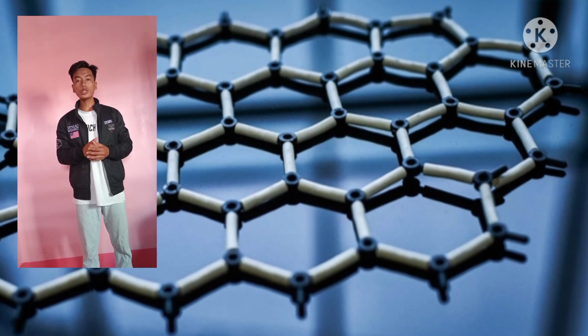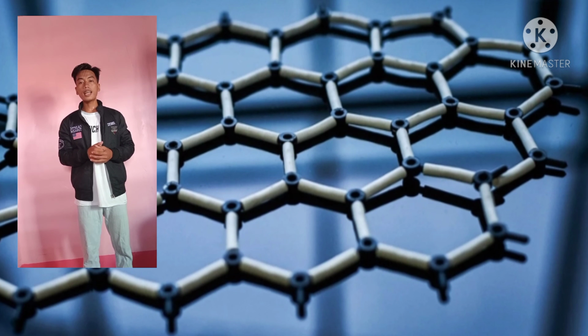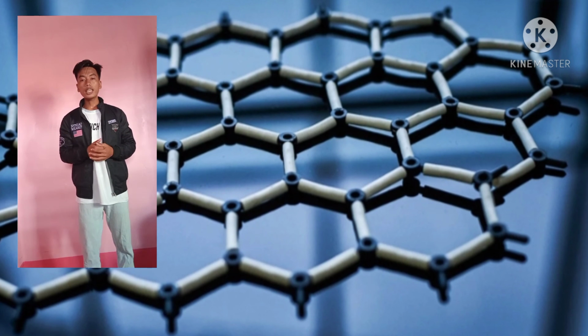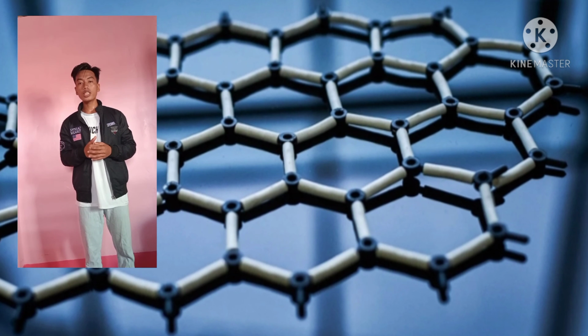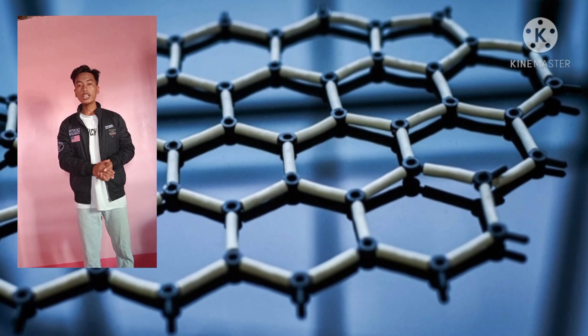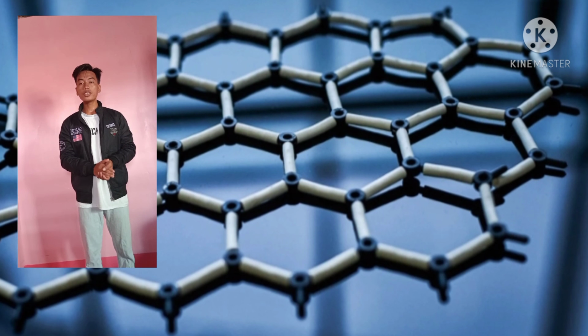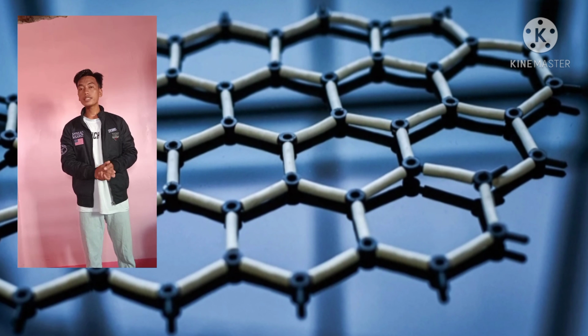A graphene supercapacitor is said to store almost as much energy as a lithium-ion battery, charge and discharge in seconds, and maintain all this over tens of thousands of charging cycles. One of the ways to achieve this is by using a highly porous form of graphene with a large internal surface area, made by packing graphene powder into a coin-shaped cell and then drying and pressing it.